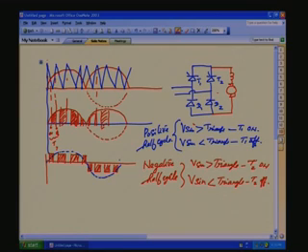But what is the advantage? Because of the pulsed waveform, these pulses have high frequency components. So, the harmonic currents drawn by the load will be much less compared to the previous schemes. So, this way the efficiency of the system can be improved. At the same time, the output voltage can also be controlled. Here, how do you control the output voltage? We found the pulse width duration. This duration depends on the period during which the sine is greater than the triangle.